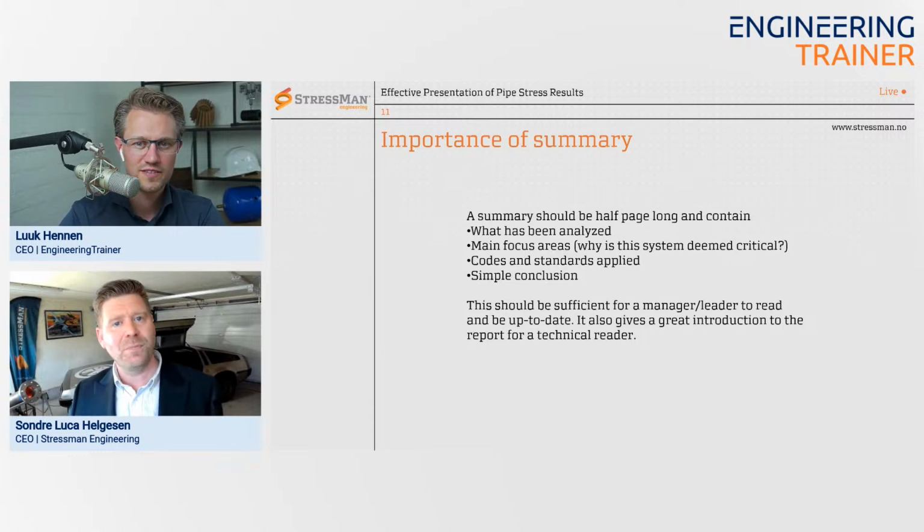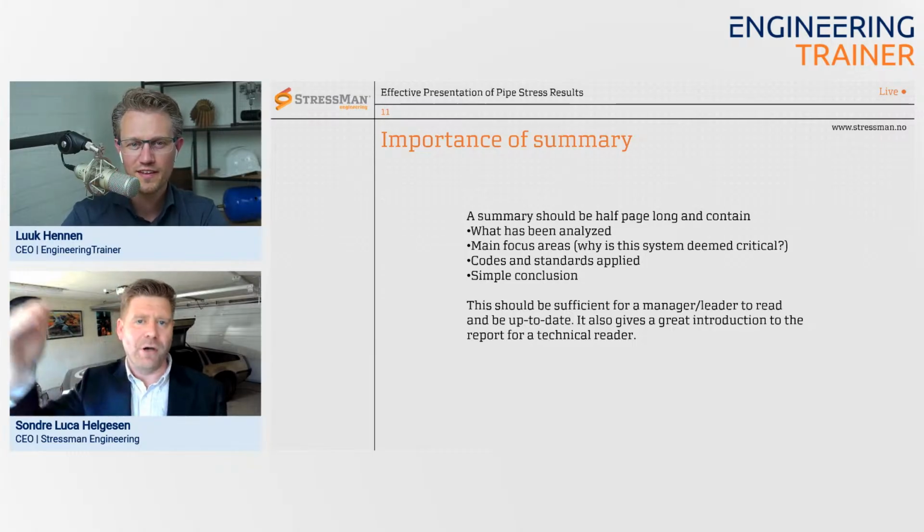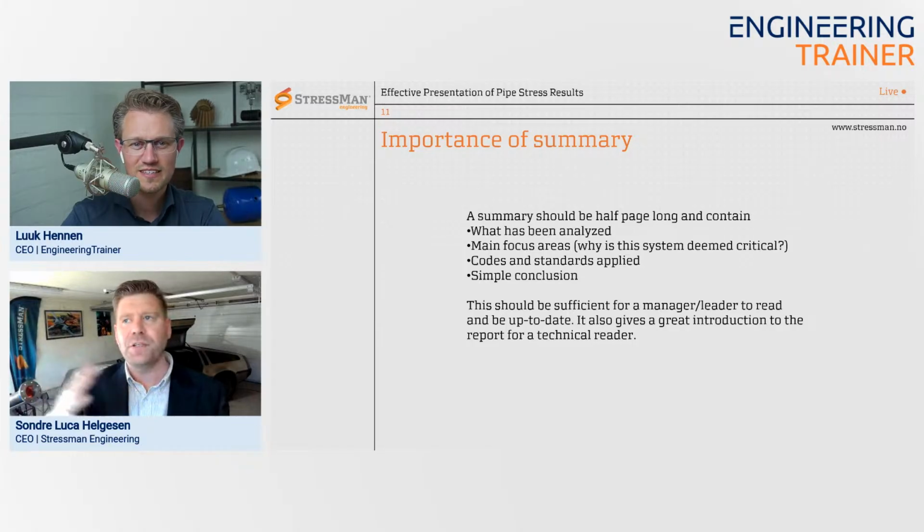Should occasional loads be a part of the pump check? Of course, it depends on the loads, but I believe no. Should we use operating, or should we use design when checking rotating equipment? I strongly believe we should use operating, because that's what the equipment will see 99.9% of the time. So even though you go above, that might be totally fine. So then these kind of discussions kick in. I see a lot of our clients already specify use the operating temperature when checking the equipment loads on rotating equipment.